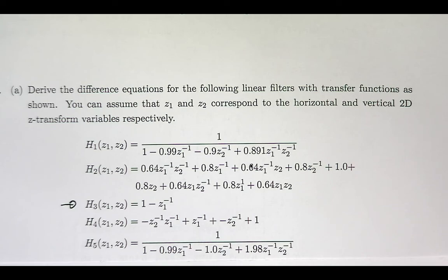First of all, when you see that, is that an FIR or IIR filter? Maybe go through them all and just say which one is which, okay? So the first one, H1, is it an IIR filter or is it an FIR filter? Who's in favor of FIR filter? Who's in favor of IIR filter? All right, correct. It's an IIR filter, okay?